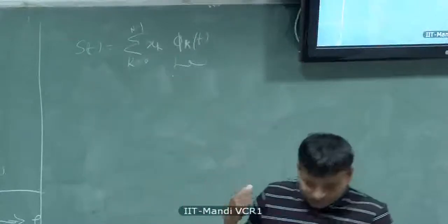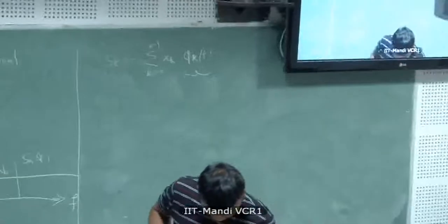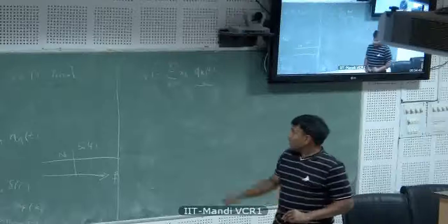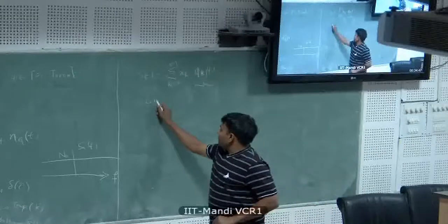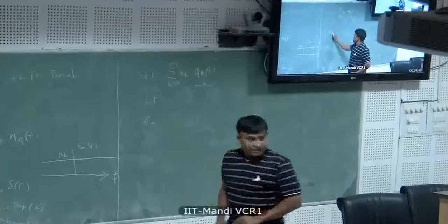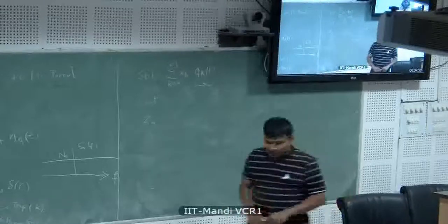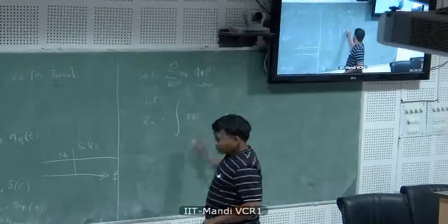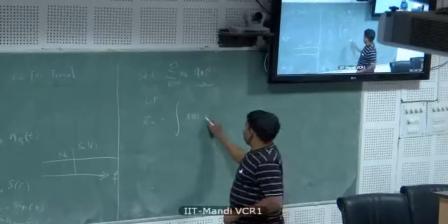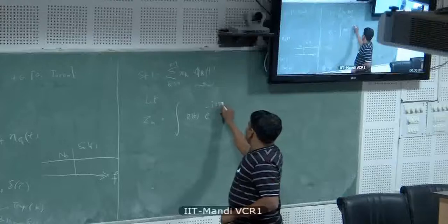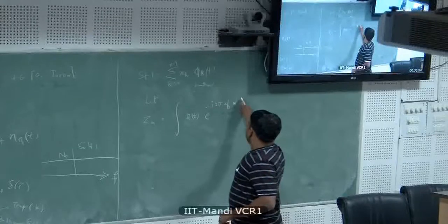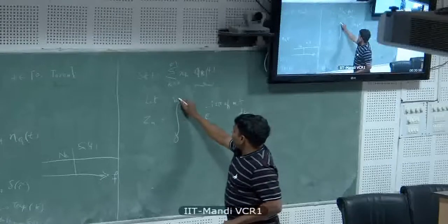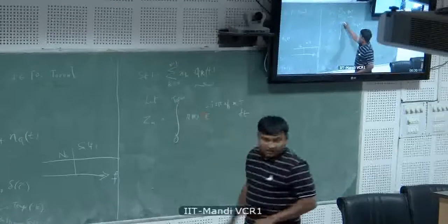So we're going to develop our OFDM receiver now. Let z of m, it is just a variable, be equal to the received signal r of t multiplied with e to the power of minus j 2 pi delta f m t dt and integrated over 0 to T OFDM because our signals are time limited.